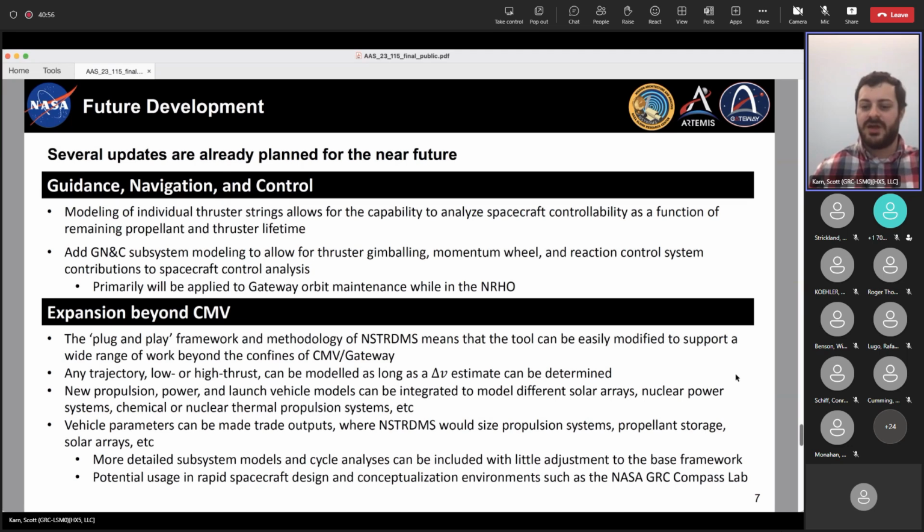The really critical thing there is that you have to make a lot of assumptions in order to get this framework to work. For something like a hybrid mission, the amount of EP delta V that you need to expend is very sensitive to the size of your chemical stage, the duration of your mission, and what your destination is. So you might have to do a lot of work to get this simple methodology to work for a complex mission like that. But without actually going through and doing the work, I wouldn't be able to tell you how hard that would be.